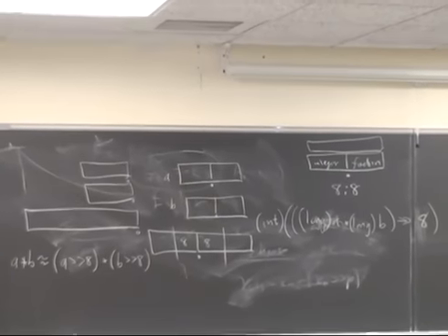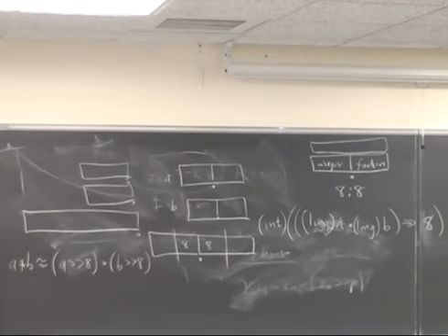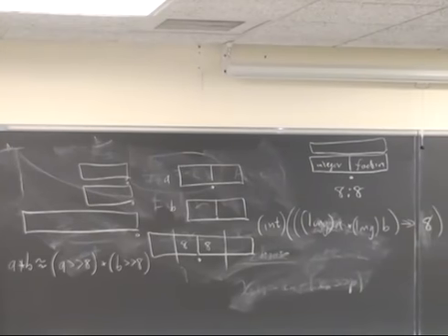Now, the reason we can get away with this is that in the end, at the bottom of this process, we're going to be putting the number out into an 8-bit pulse width modulator. That is to say, the total precision that we have at the end of the process is 8 bits. And so we can afford to throw away the low order digits because they almost don't matter.